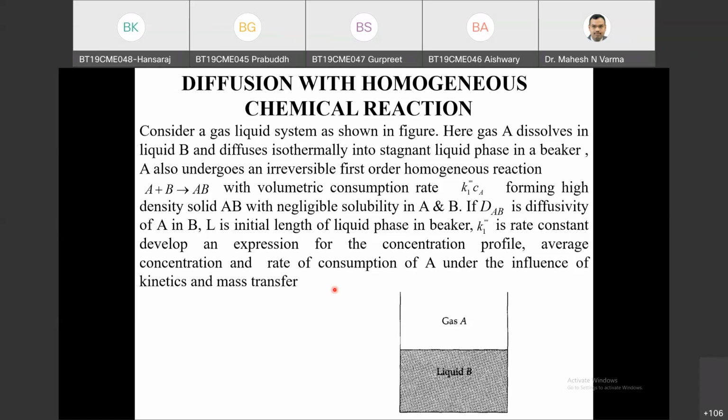Actually, this is enough in transport phenomena, and you will be confident once you assume whatever needed information, whatever needed concentration profile. And what is the expected concentration profile? Roll number 49, Harshavardhan. Expected concentration profile: where will you get the highest concentration? Sir, at Z equal to 0, we will have CA naught. Yeah, you will have CA naught at Z equals to 0.